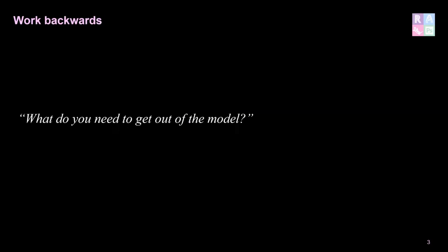So a good tip for you is to work backwards. What do you need out of that model at the end of the day? Is this a visualization model, as in one that's going to be rendered? So the quality of the sofa, as an example, has to be photorealistic? Very doubtful. When it comes to a Revit model, particularly when you're doing working drawings, it's more of an idea that you need to know that the sofa is of this size and this location within the model.